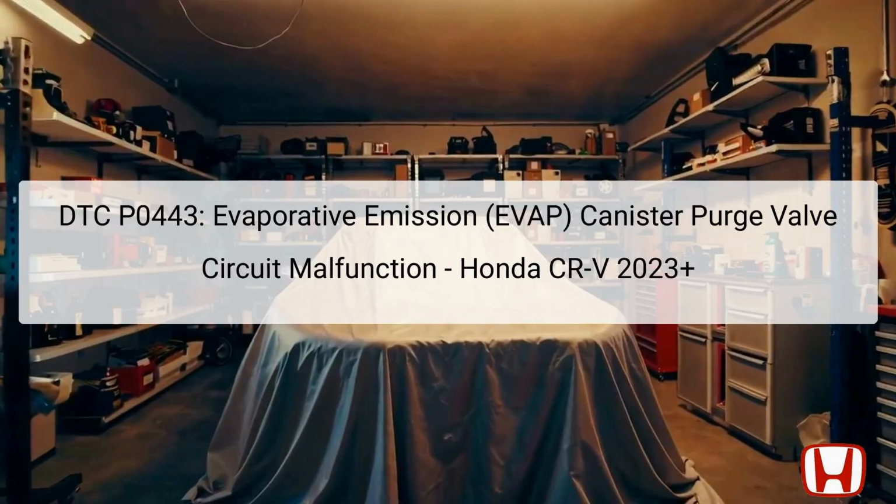The DTC P0443 signifies a malfunction in the evaporative emission (EVAP) canister purge valve circuit. This component plays a crucial role in controlling fuel vapor emissions from the fuel tank, allowing trapped vapors to be directed into the engine for combustion. When the powertrain control module (PCM) detects the return signal from the EVAP canister purge valve does not correspond with the expected output signals, it stores this diagnostic trouble code.